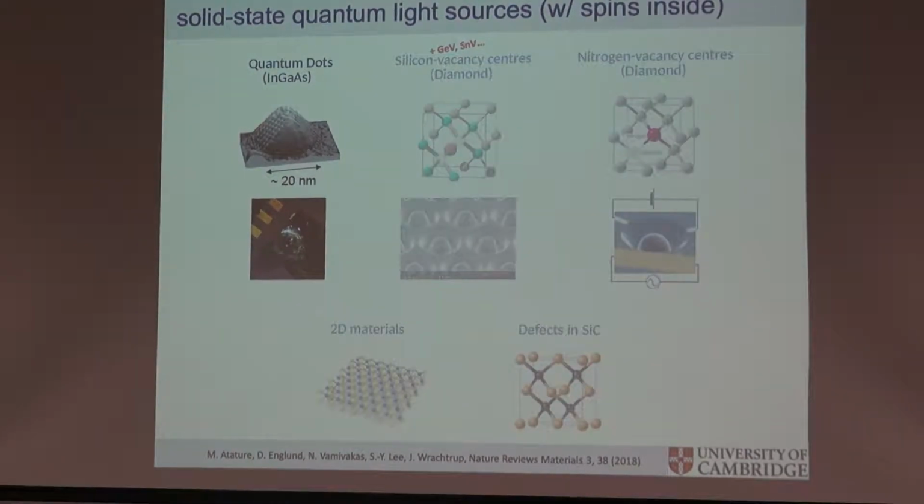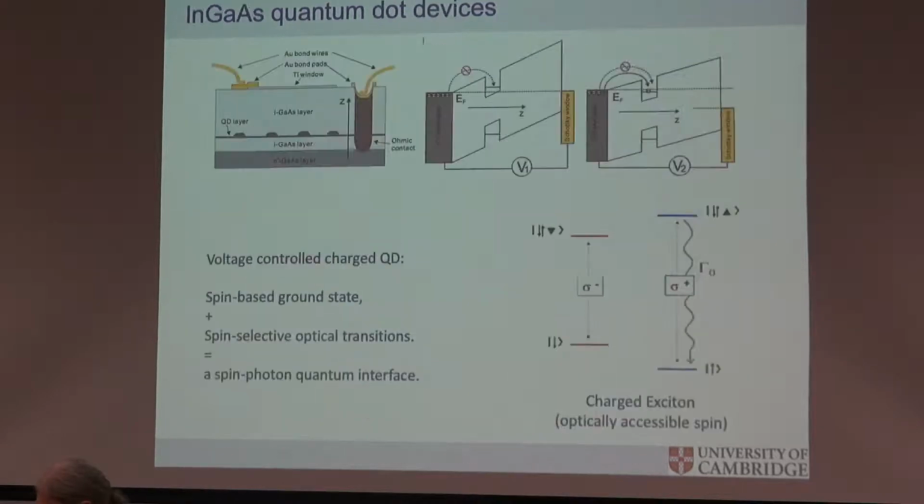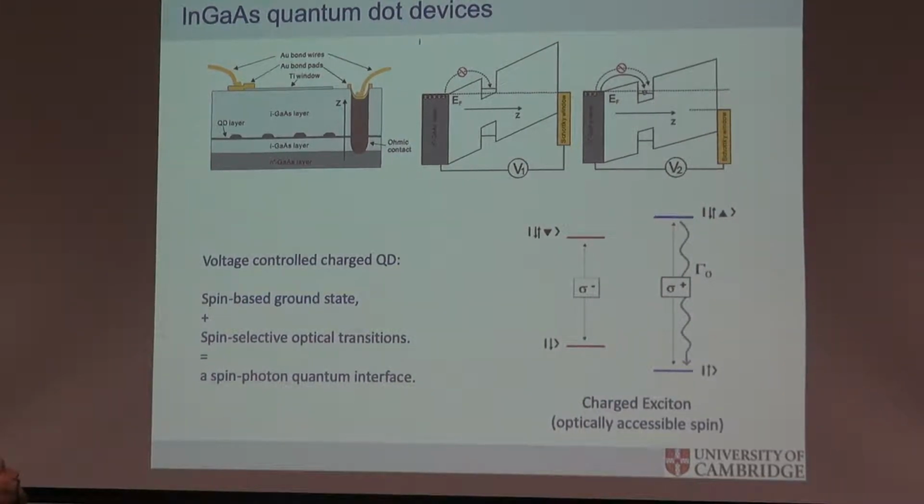But I'll start with talking about quantum dots. All right. So what do I mean by quantum dots? These are semiconductors. Indium arsenide is a direct bandgap material. There's work going on here as well on this particular system. It's basically a small island of about 20 nanometers to 3 nanometers, little pancakes, trapped inside a larger bandgap material, gallium arsenide. All right? So it's material-based confinement for excitons or electrons and holes separately. That is our starting point.